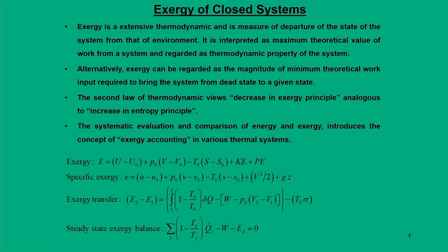Now, in some situations when there is a work input to the system, we can say that exergy is regarded as the magnitude of the minimum theoretical work input required to bring the system from the dead state to the given state. In other words, when the system moves from its original state to the dead state, it produces work output. When it moves from the dead state to a given or any arbitrary state, then it is the work input to the system.